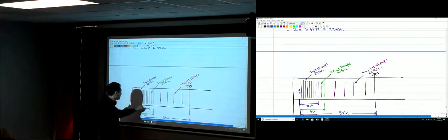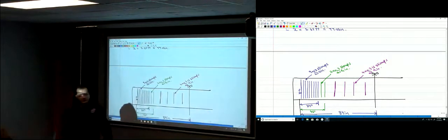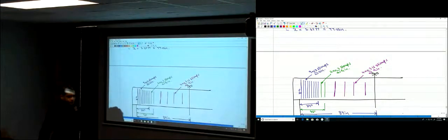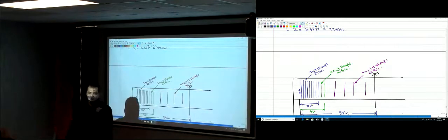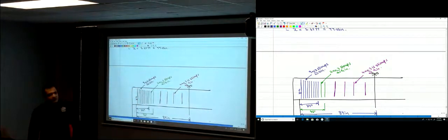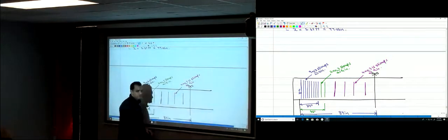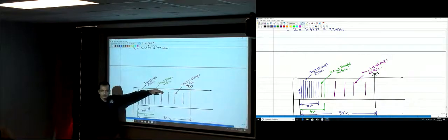What's the purpose of the longitudinal steel bars here, or on the top? Resisting the moment. Okay? The longitudinal bars on the bottom of the beam resist positive moment. Longitudinal bars on the top of the beam usually resist negative moment, or they can be used as compression steel.